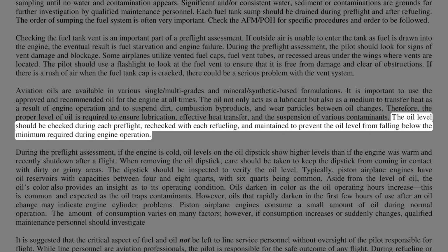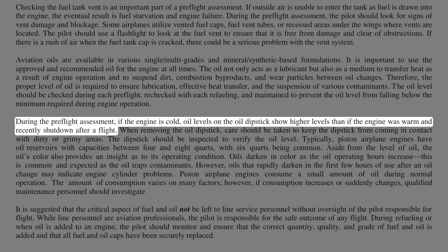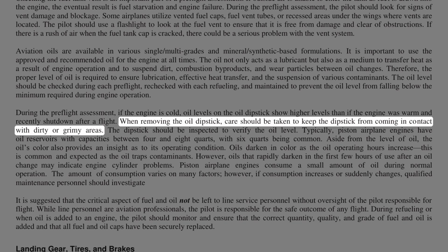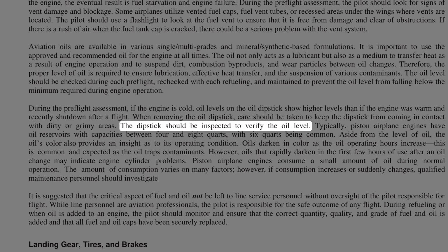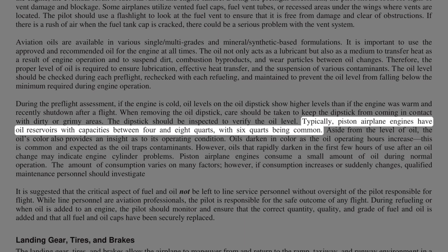The oil level should be checked during each pre-flight, rechecked with each refueling, and maintained to prevent the oil level from falling below the minimum required during engine operation. During the pre-flight assessment, if the engine is cold, oil levels on the oil dipstick show higher levels than if the engine was warm and recently shut down after a flight. When removing the oil dipstick, care should be taken to keep the dipstick from coming in contact with dirty or grimy areas. The dipstick should be inspected to verify the oil level. Typically, piston airplane engines have oil reservoirs with capacities between 4 and 8 quarts, with 6 quarts being common.